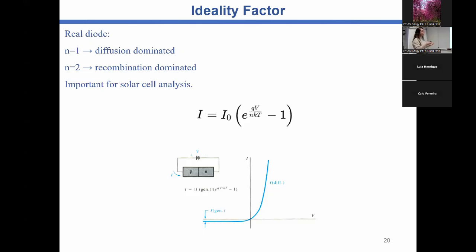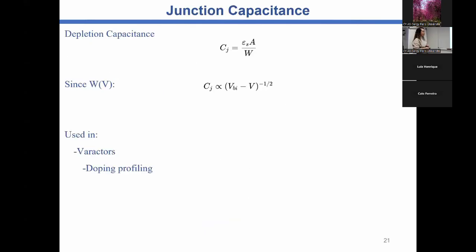And if you want to analyze your JV curve behaviors, it's quite interesting to analyze the junction. This partial charge will give one intrinsic potential depending on the doping and the properties of your materials.